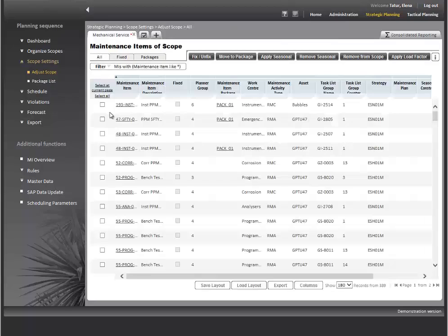It is reasonable to group operations which have to be done on the same piece of equipment or equipment which has related relationships. For example, if you have a job to replace oil in a motor, and at the same time you have a job to do an inspection test, you don't need one day to take your motor, switch it off, replace oil, then start it again, and in 1 week do another maintenance activity, like inspection test. It's not reasonable to do this. We should make maintenance time as short as possible.